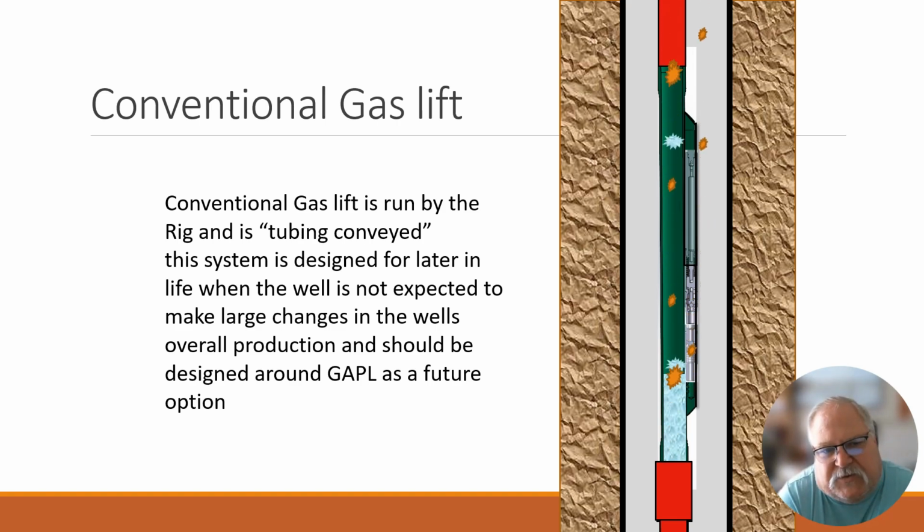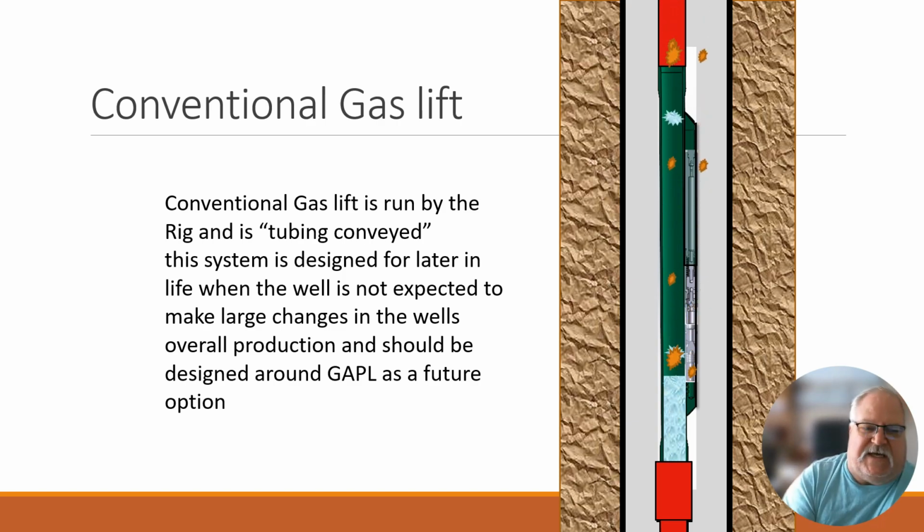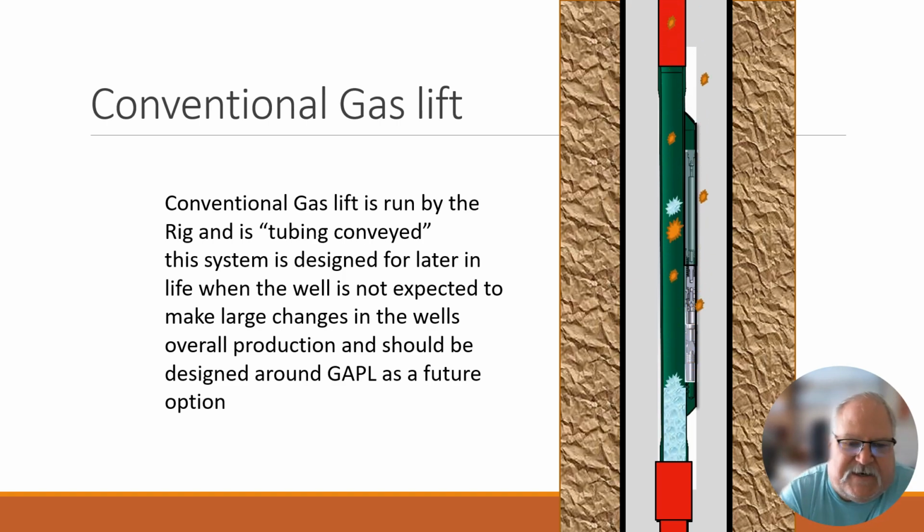So that's why you have these valves staged. As your pressures drop, as it goes deeper, the upper valves close. They require more pressure to open in the casing, and as the liquid volume's dropping, the pressure's dropping. So then upper valves close, and it slowly stages down.